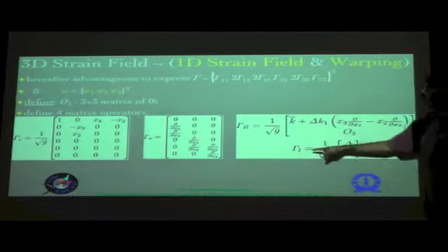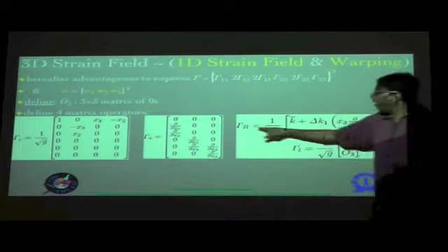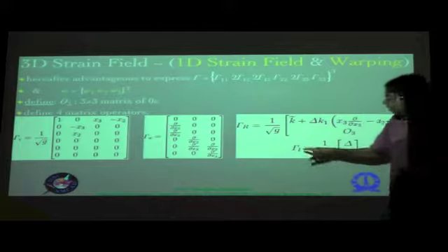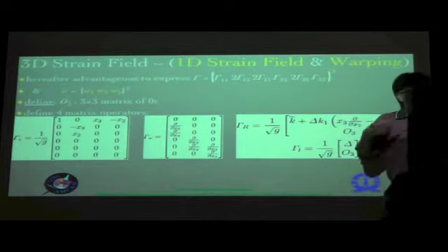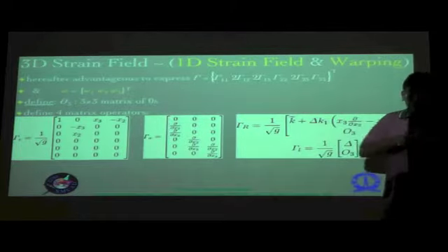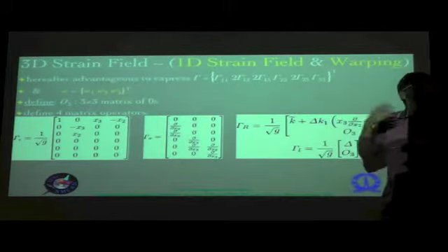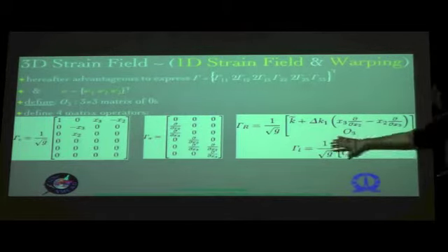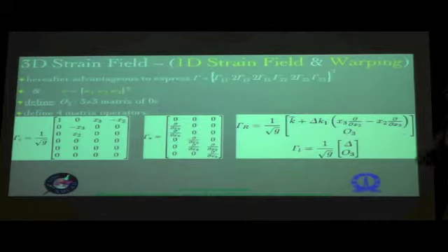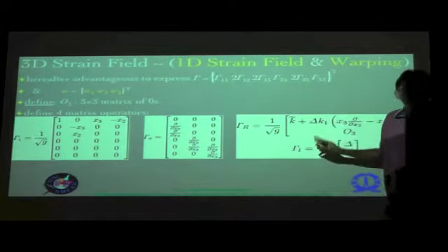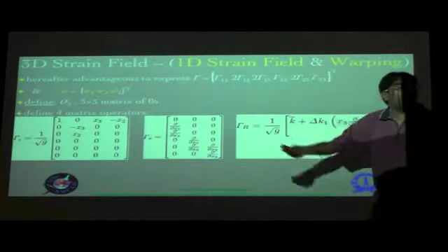And finally, you have a gamma subscript L. This R, of course, refers to the fact that it is associated with initial twists and curvatures. Now coming to L, these are associated with the derivatives of the warping with respect to the length coordinate, which is x1. So basically involving the w primes, w1 prime, w2 prime, w3 prime, etc. So that is why you have this gamma L. So once you have defined these 4 operators, 2 of which are differential operators and 2 of which are just operators which just multiply other matrices.